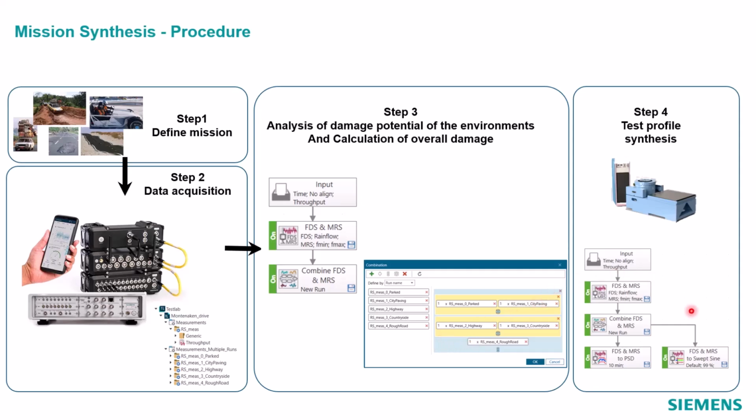And then from there, we want to synthesize an accelerated PSD from the fatigue damage spectra. And this PSD will have an equivalent damage to the lifetime field data. And so we've implemented this in TestLab as well. Here you see the generic mission synthesis approach in TestLab, where we calculate the fatigue damage spectrum and the MRS. We combine those different environments together using this combination block, and then we synthesize either a PSD test or a swept sine test with an accelerated lifetime but an equivalent damage to those components.